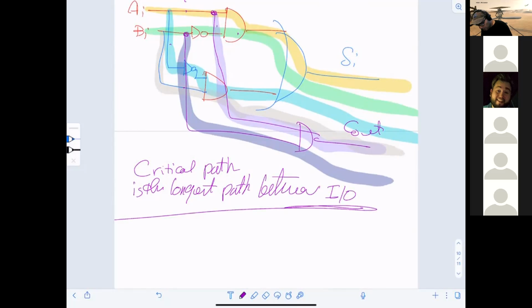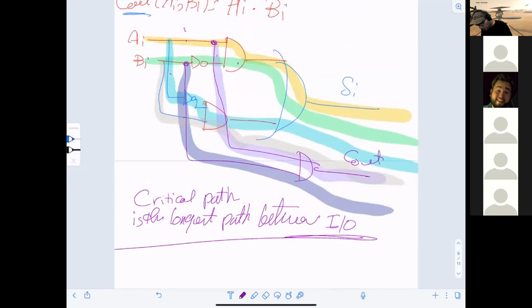Normally, when we are in a race, the fastest is the winner. For us to make the circuit stable, the slowest is the winner. So even without knowing the weight of everyone, you will find the longest path is this one.